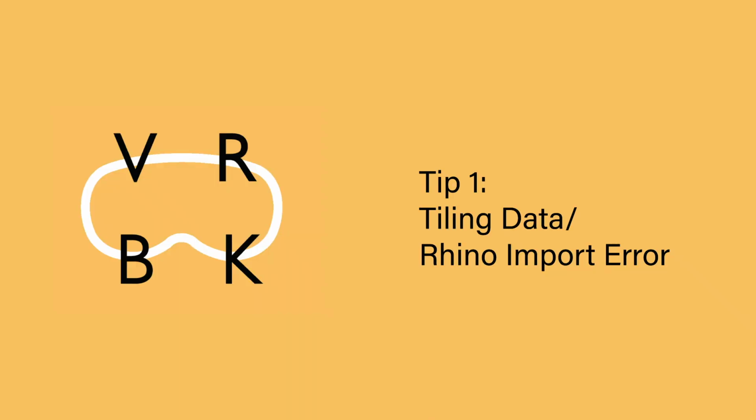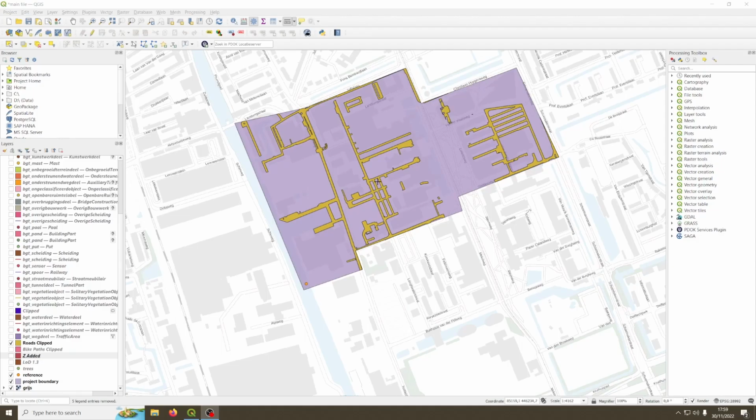One issue that you might run into is that when you export one of your layers in QGIS to Rhino, the hatch that you get is too big for Rhino to handle. This might happen if your project area is very large, or if the layer that you're exporting is very complex, like the road system, for example.